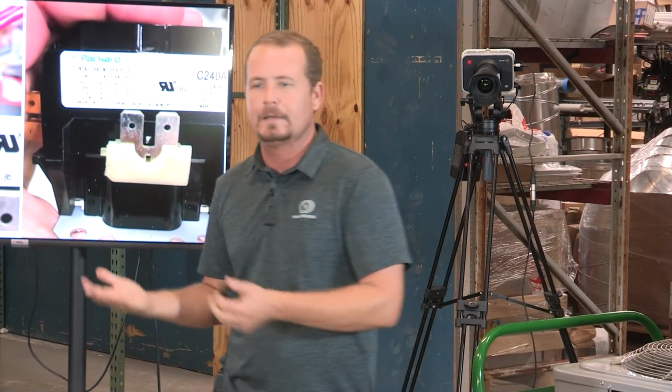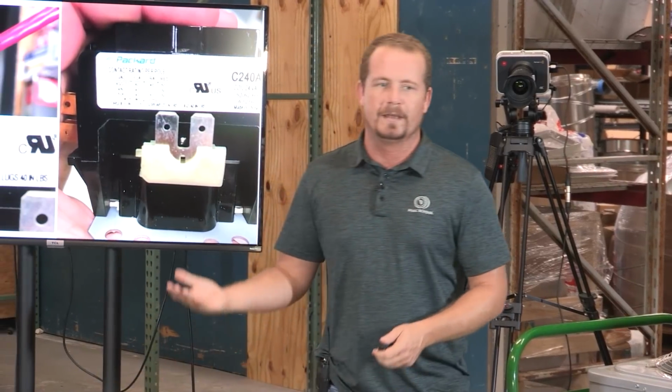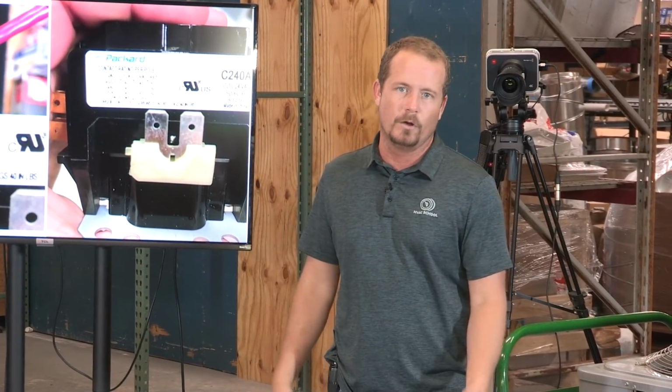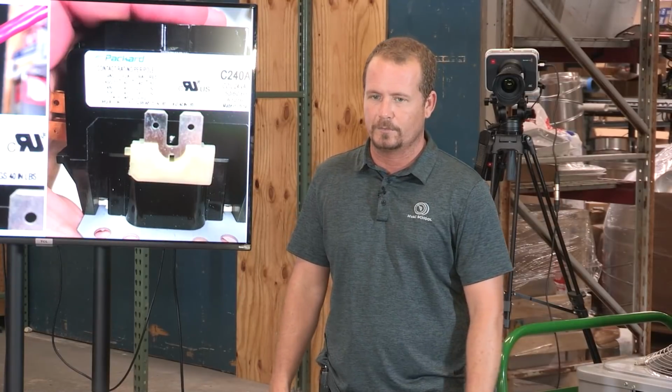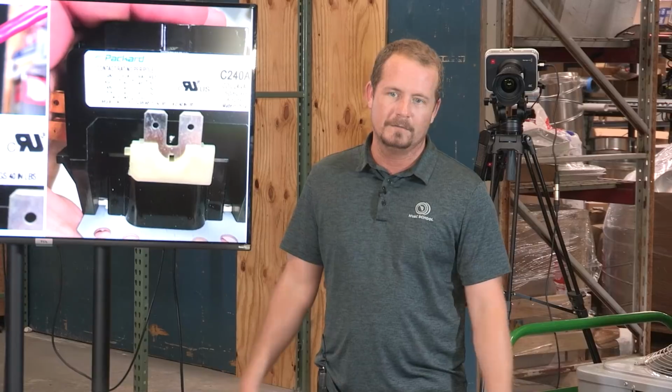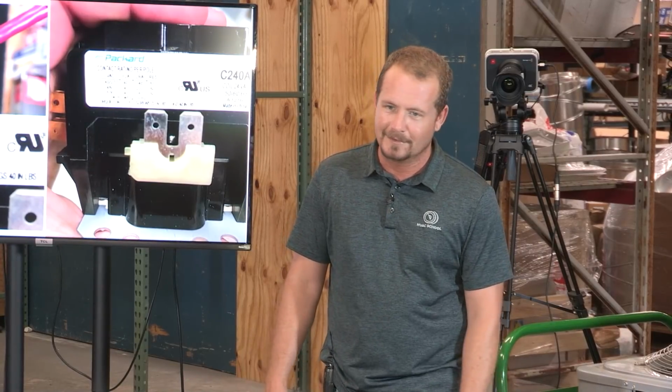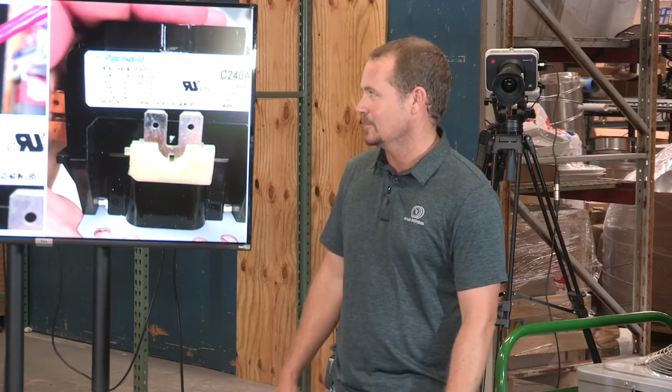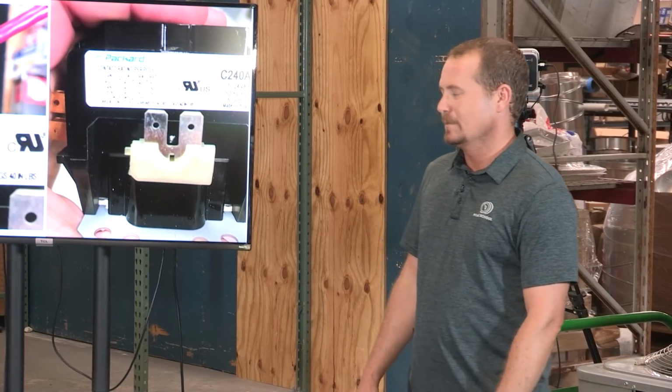But again, unlikely, because residential equipment is designed to go all the way down to 208 anyway, because it's designed to also work in three phase. Maybe if you're doing a sub panel in an outbuilding or something. Yep, if you're feeding a sub, maybe you have a sub shop, right? You're making some delicious submarine sandwiches. That could do it. You shouldn't put those in your house.